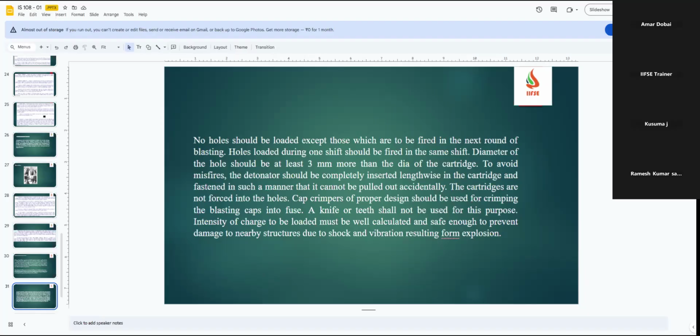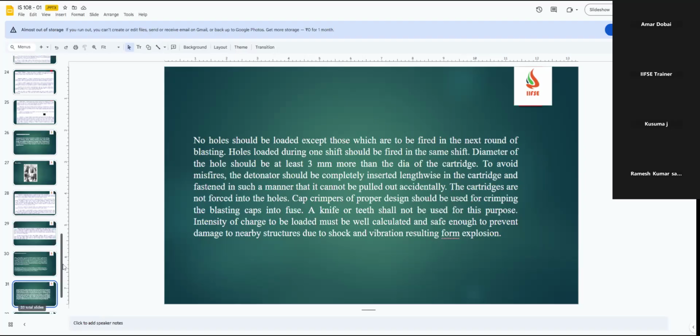So they will use these rubber mats, which weigh 2 to 3 ton or 4 to 5 ton, even sometimes 6 to 7 ton. They add many rubber mats joined together, then use this rubber mat over that, then above the rubber mat again they will apply loose soil so that it can prevent the flying particles and also the impact of the blast. Somehow it can reduce the impact to the maximum so that we can safeguard the people from the flying particles.